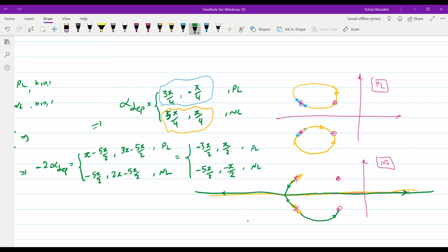We can find the angle of arrival at the zeros, but we have two zeros here, so there will be another branch arriving at this. Basically, we have this branch moving towards plus infinity, the other branch goes towards minus infinity, but here we have no asymptotes. Therefore, that branch will come back towards the origin from the positive side.